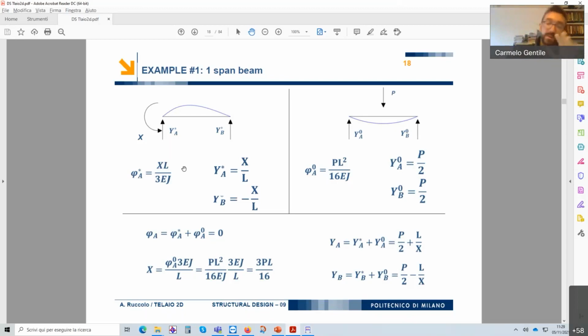Okay. So let's go back from the beginning. If I have a statically determined structure, the distribution of force never depends on the stiffness distribution, so I can solve the structure, find the reactions, find the internal forces, never wondering what the material is.